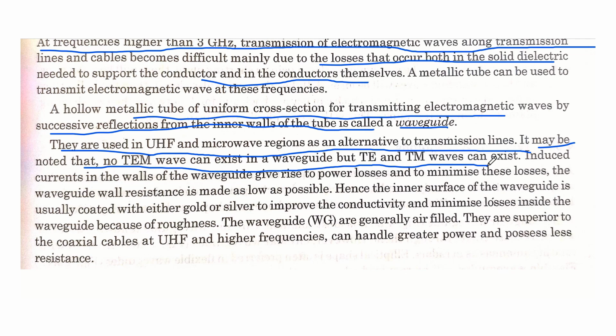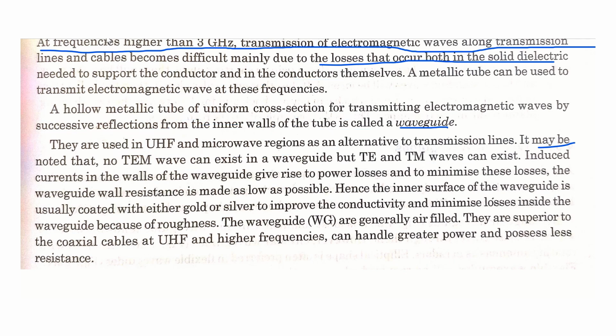It means we know in free space we transmit TEM waves. TEM wave is a transverse electromagnetic wave, which means the electric field and magnetic field are perpendicular to the propagation direction. But in a TE wave and in a TM wave, only either the electric or the magnetic field exists, propagating perpendicular to the propagation direction. Okay, here the waveguides don't support the TEM wave. Remember this point also, it's very important.